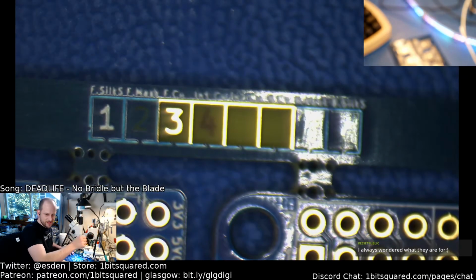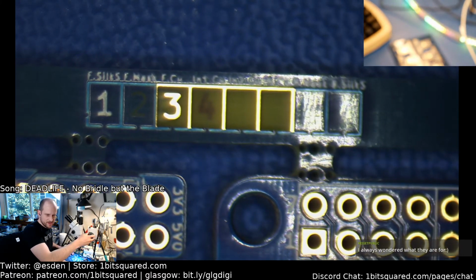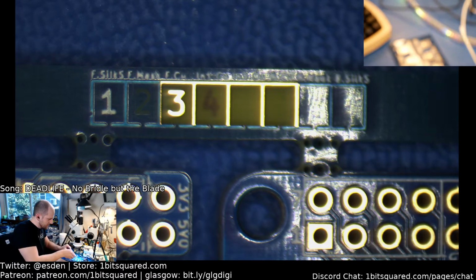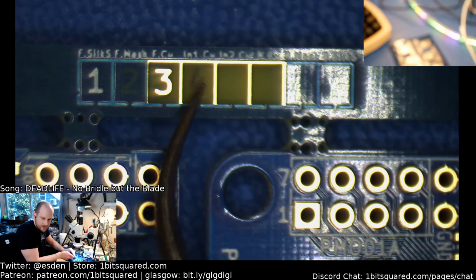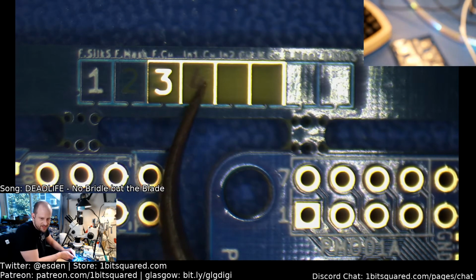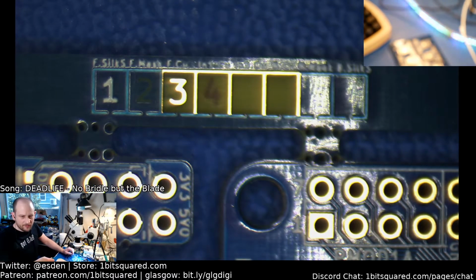Yeah, so this is how this looks. And you see very faintly, let me get tweezers, you see faintly this 4 here shining through the layer. So there's a thin pre-preg. How the PCB is put together: you have a fairly chunky PCB material that has copper on top and bottom first, and this is inner layer 1 and inner layer 2.